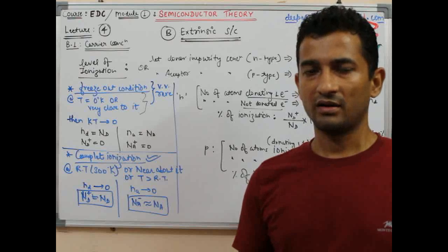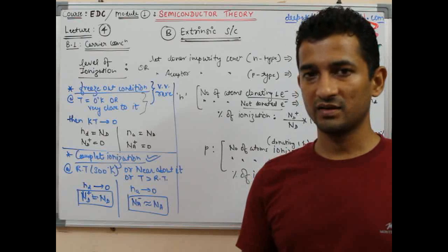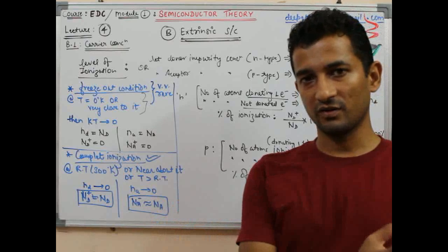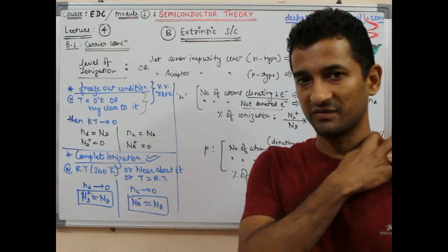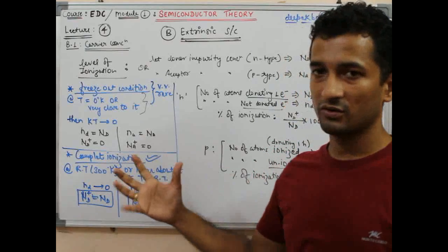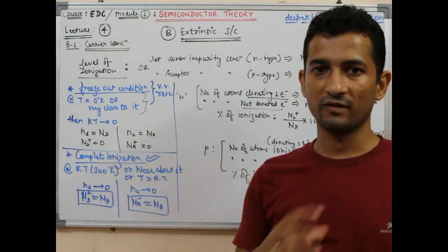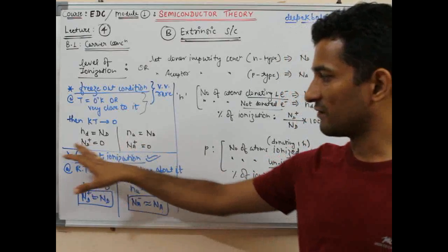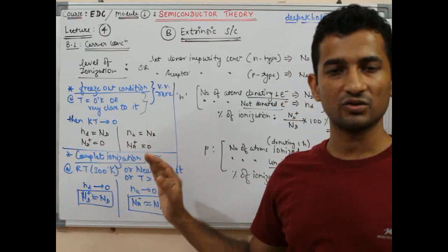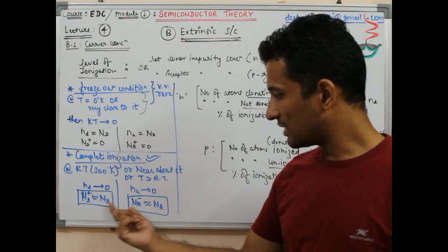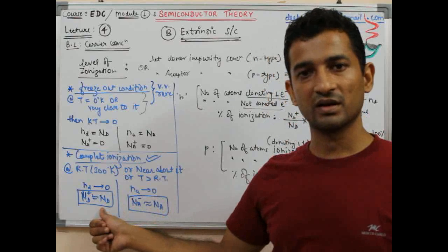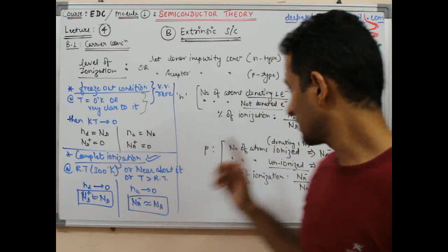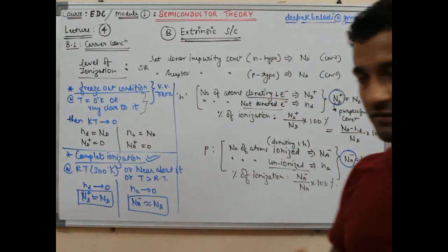After lots of study we have identified that with silicon the probability of complete ionization is very high for phosphorus specifically, and similarly for boron specifically. So after that we conclude that silicon with phosphorus for n-type or with boron for p-type is a good combination. So we will always be considering this case if nothing is mentioned. From now onwards I'll take Nd and Na symbols only, assuming complete ionization. But now we know how to proceed if it is not the case of complete ionization.